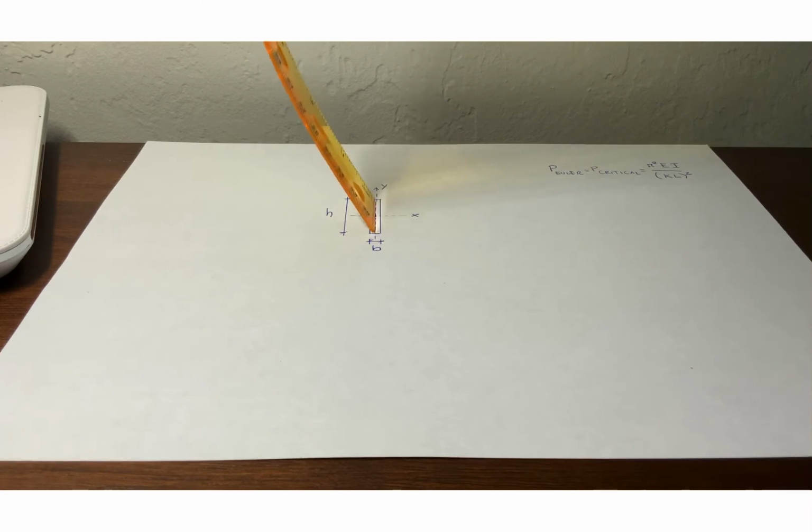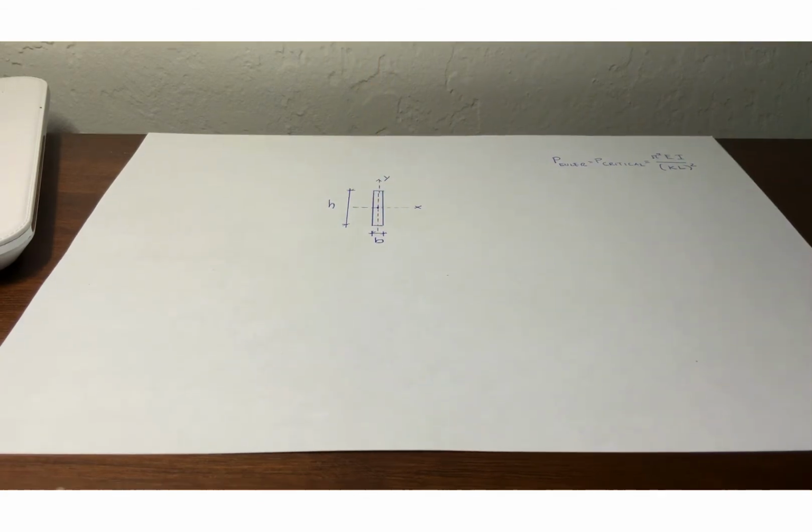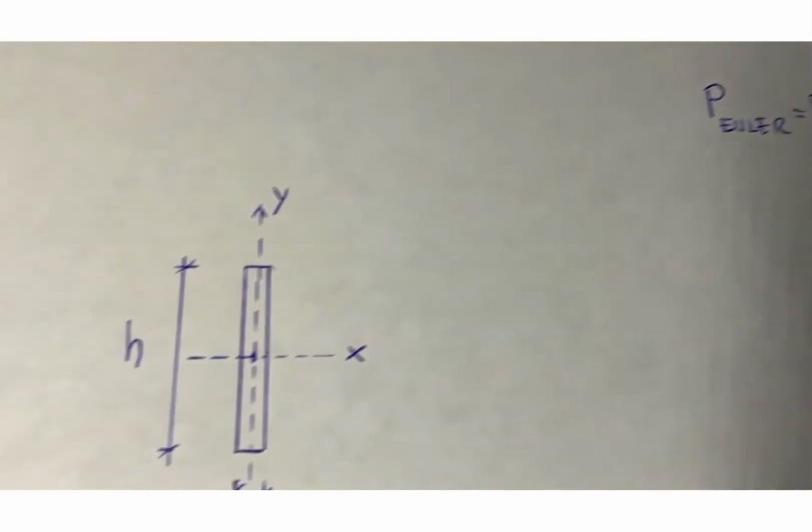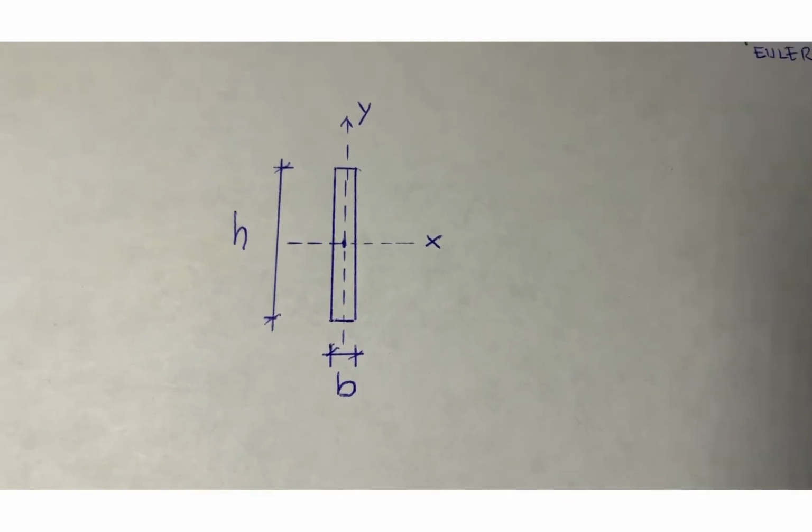about the y-axis, not the x-axis. What does that mean? As you know, in the area moment of inertia, for B smaller than H, Ix will be greater than Iy. And with that, if the column is in compression, the member tends to buckle about the y-axis, not the x-axis, in the case that I show in here, in the weakest direction. And with that, for the I in that equation, you need to determine the Iy if we define the cross section in this way.